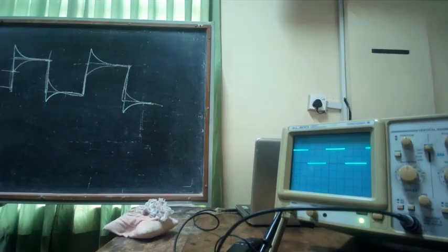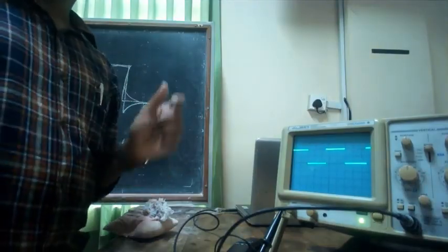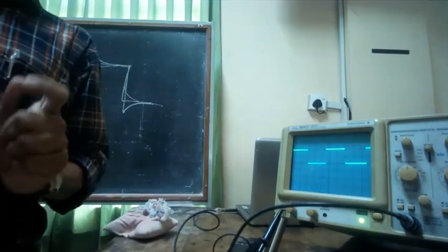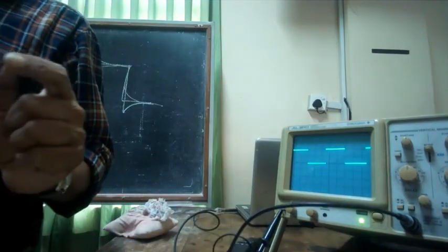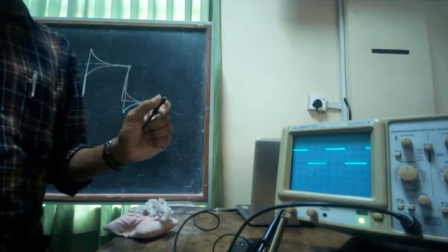Okay, understand this. Later on you should be able to prove all this using circuit analysis, but right now we are not expecting that. Later on you will learn how to do it. So that is why you have this tuning, called probe tuning. This is only applicable if you put it into 10 mode. In 1 mode you don't have to do probe tuning, right? Any probe will work in 1 mode. You don't have to worry about that.